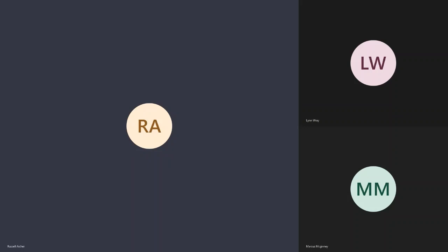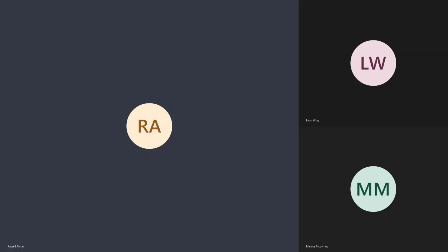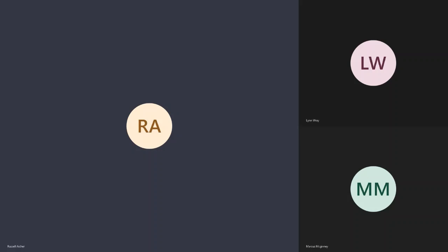For GIS, the coverage format has a strong topology, okay? You don't have to worry about it, but if you wanted a polygon layer, you had to build the polygon layer, it made sure everything connected, and if it didn't connect, you got errors and you had to go back in and fix them. If you wanted a line layer, same thing. Shapefile format has a really weak topology. Basically, all it does is say this connects to this, and this is the order. That's about as strong as it gets.